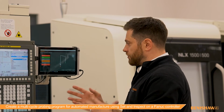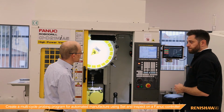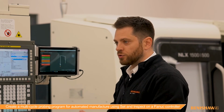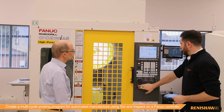So now we've got that, it's a similar situation to other programming methods. We just hit the send button. That's going to send that program to the NC and upload it ready to run. Great. Straight over the Ethernet. That's right, absolutely. Because this is a self-contained program, with tool change and switch on, we don't have to do anything else. We simply need to stick it into memory and we can now run that cycle.